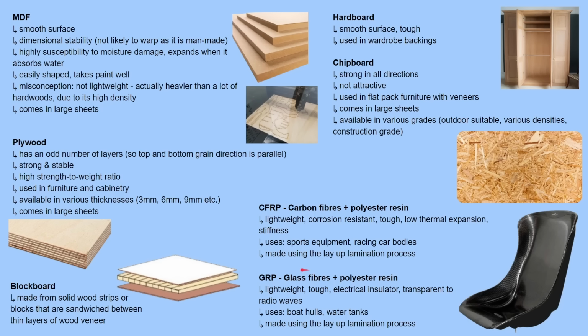And then glass reinforced plastic, similar thing, using glass fibers and polyester resin. It's lightweight, tough, it's an electrical insulator, it's transparent to radio waves, it's used in boats, in boat hulls, water tanks, and just like carbon fiber reinforced plastic, is made using the layup lamination process.